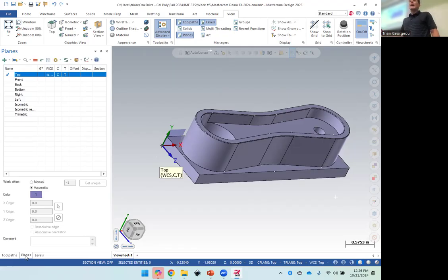Now, if you had design intent, I thought I did, and I realized SolidWorks and Mastercam are like 90 degrees off on the planes. So I'm not going to make the joke. So that corner is where we want it, right? I specified in our drawing, if you look, G54 Z0 set at bottom of stock, top of parallels.